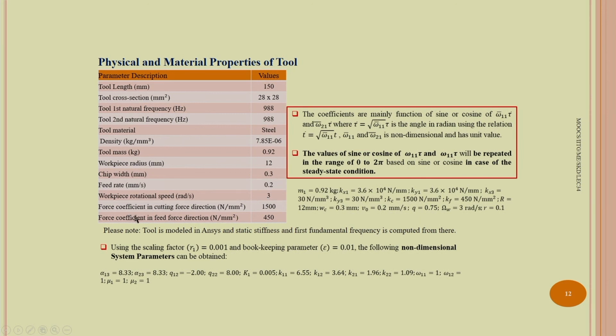second. The force coefficient in the cutting force direction is taken to be 1500 Newton per mm square, and the force coefficient in the feed force direction is taken to be 450. So, taking these parameters, the other parameters are obtained.